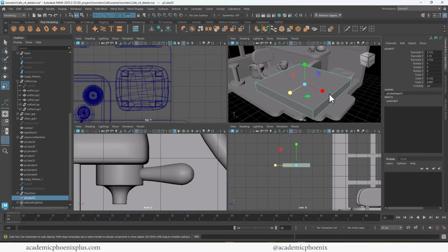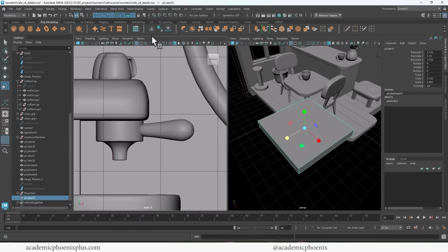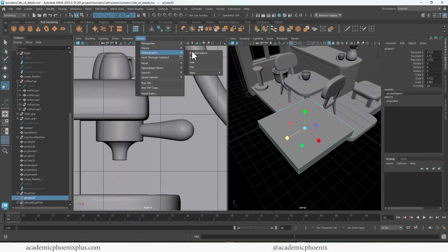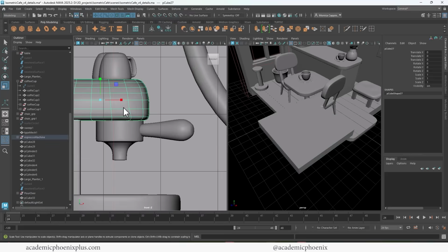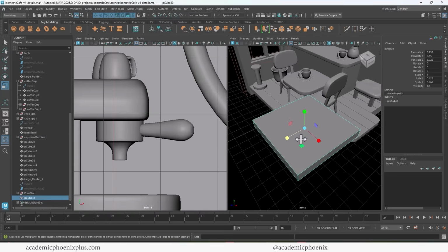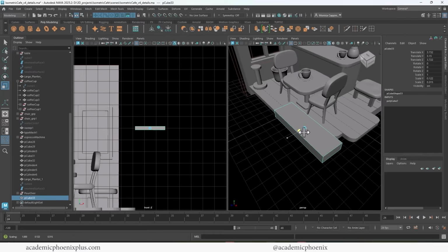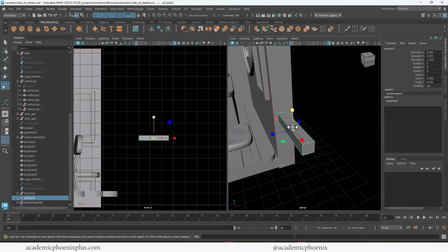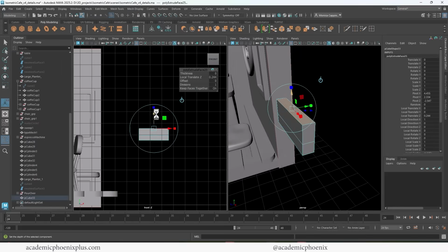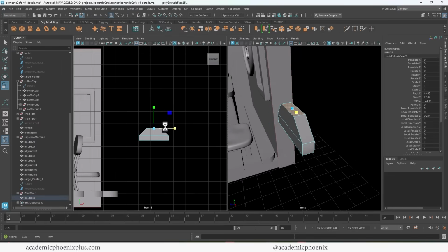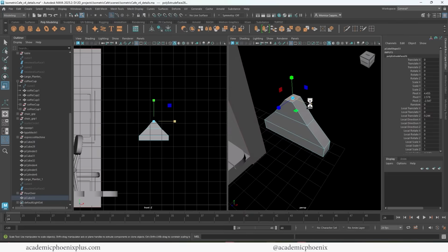Let me focus. And I'm actually going to go to two views. I'm going to go into the orthographic side view, which I think I'm already in. There it is. And I'm also going to scale this flat. So let's start off by grabbing the top face and we're going to extrude and lift, and we're going to make this pretty skinny. Extrude, lift, skinny. So you make sure that when you're scaling it, you're grabbing it from the side, not uniformly, because we don't want it to have thickness. We're just trying to do the silhouette right now.